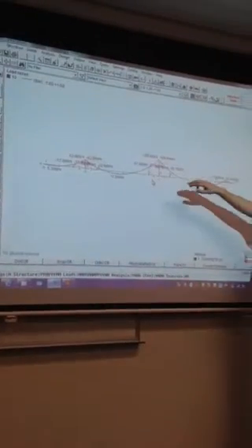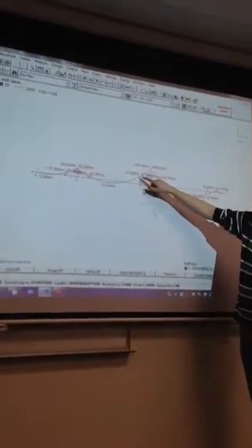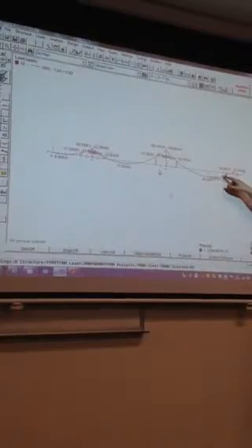So you've actually got two bending moments to check, and you would choose the reinforcement that's the greater of those two, okay? So you might find that here is critical, you might find here is critical, all right? When we're looking at our positive bending moment, positive is sagging, so we'd only be designing based on a 250 thick slab.